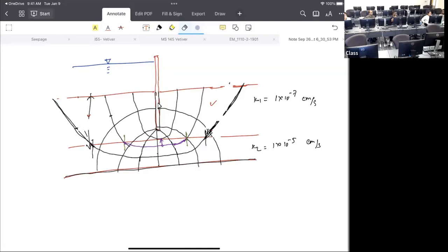Okay, now if you look at the bottom layer, it's already been a rectangle. So it's been adjusted. So we're just going to adjust the flow net, not the equipotential lines. Either way you can do it: either you do the flow lines or you do the equipotential. But it has to flow through all the way.